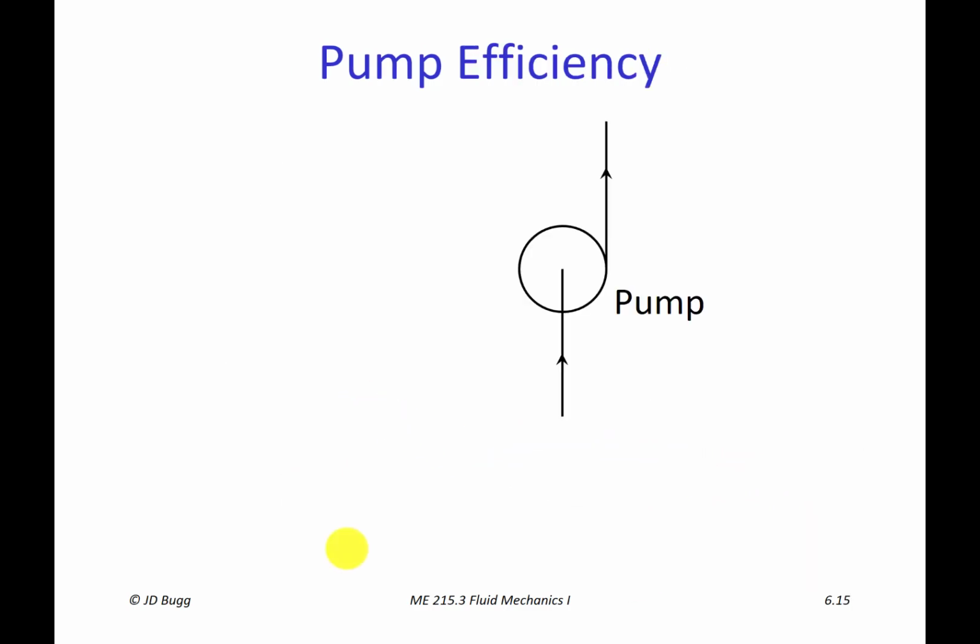Next, we want to revisit the idea of pump efficiency and just define a couple of new terms that are in common use in the pump industry. So remember, this is our little schematic diagram for a pump. And we discussed earlier that the rate at which the pump does work on the fluid is the product of the volume flow rate through it and the pressure increase across the pump.